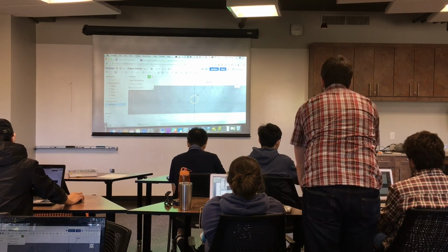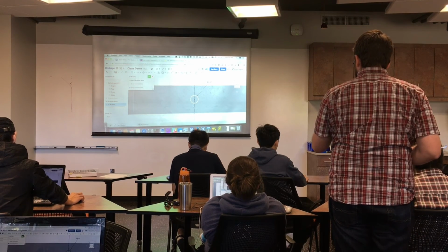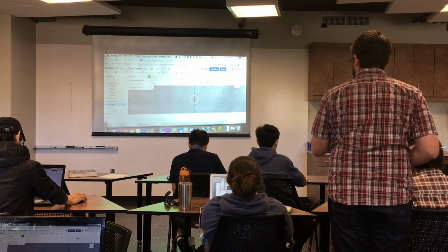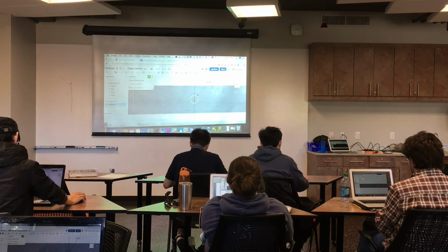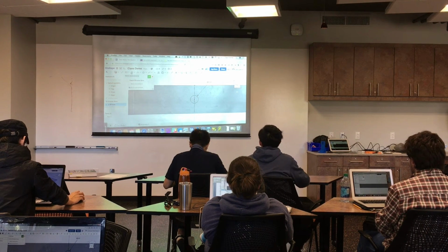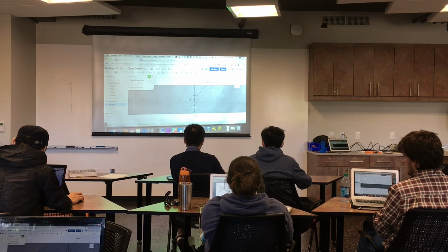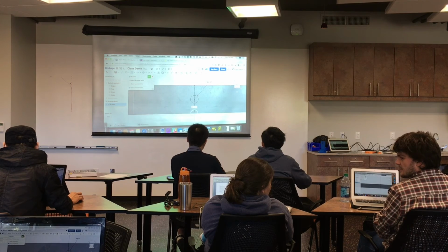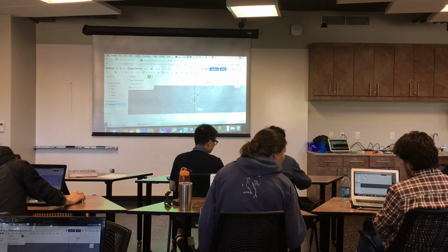Oh, so where you clicked it, you've actually constrained it to be on the origin, which is why it won't move. So here's what happened. I'll show you on here. If we do a circle, see you had the origin highlighted when you did this, and so it's constrained to live on the origin. So just delete it and draw one out here.